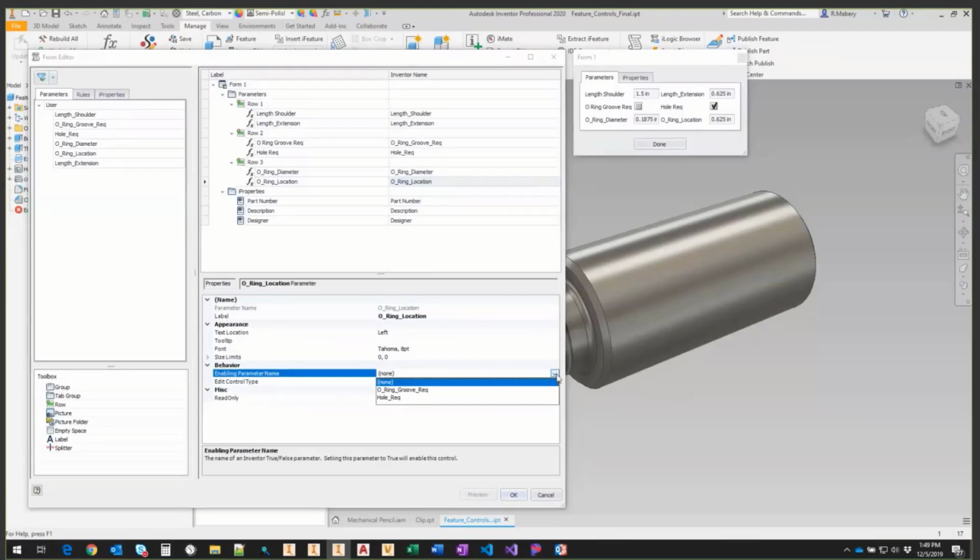If that Boolean is true, then that control is going to be enabled. If that Boolean is false, then that control will not be enabled. It just grays it out. It doesn't disappear. It doesn't hide visibility at all. You can't do any other type of control over it like you could maybe in Visual Studio. But again, this is the very basic portion of building forms inside of iLogic.